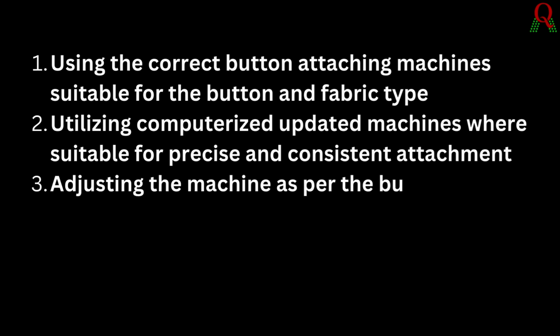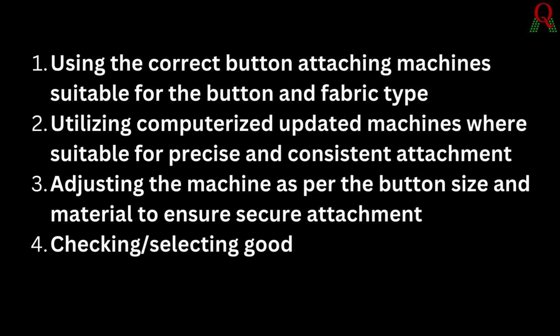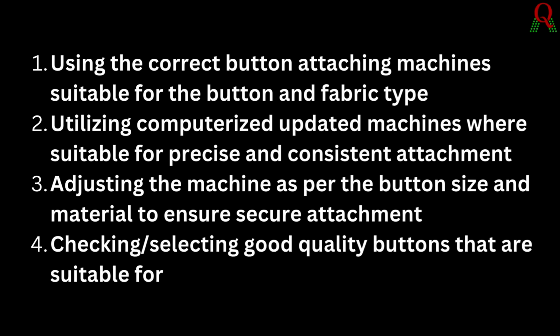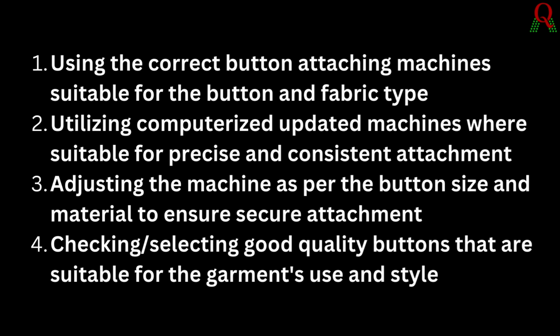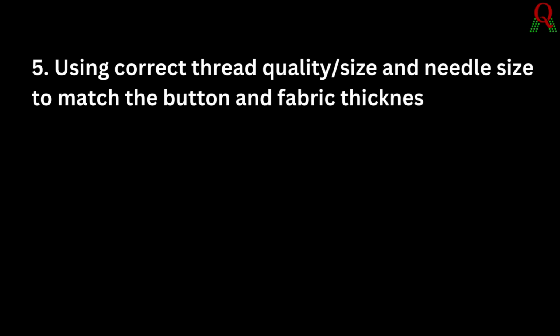Adjusting the machine as per the button size and material to ensure secure attachment. Checking or selecting good quality buttons that are suitable for the garment's use and style. Using correct thread quality or size and needle size to match the button and fabric thickness.